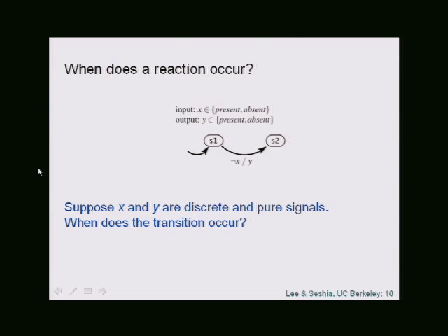Isn't there also a problem if an event happens during another event? You have multiple events firing. What order are they supposed to be processed? Okay, so Ryan has a good point here. This little example had only one event, an input event, a pure signal. But you could have multiple pure signals, and clearly then you have Boolean combinations of events being present and absent. Let's say there are two events X and Z that are both present, but at different instants. Which one do you react to? The first event that comes or the second? That decision would depend on the model that you have.